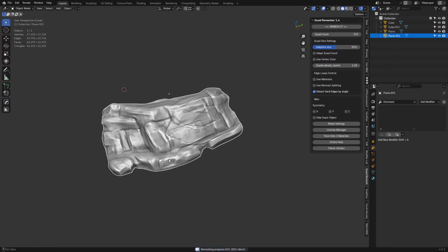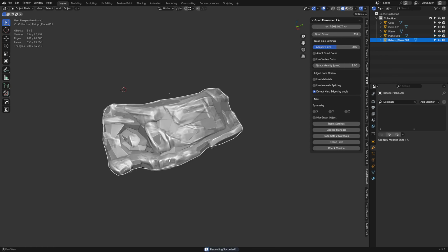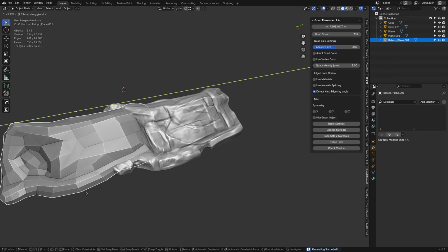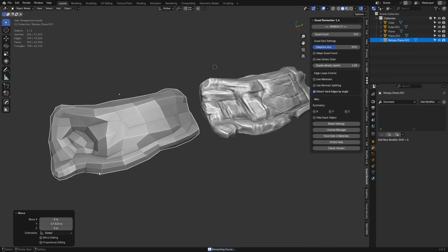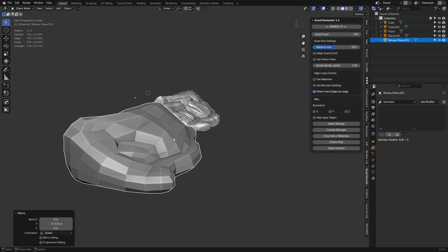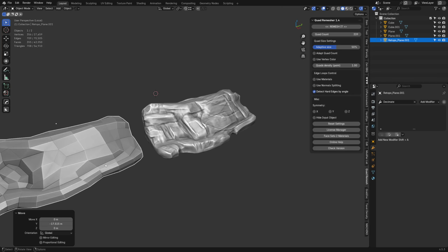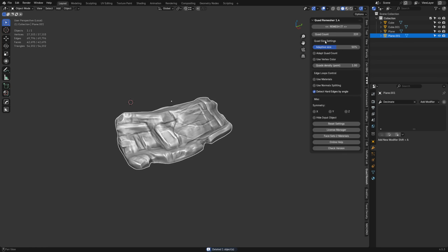The thing that usually happens with Quad Remesher doing something like this, though, is a lot of times it'll turn out a mesh, but it gets too soft and it becomes kind of okayish. It's not really that great. So what I found you can do sometimes that is useful is you make it lower than you probably want it. There are other ways of doing this, like native Blender as well, without add-ons. You shrink wrap it basically with a subdivision or something on it. You might be able to use that.